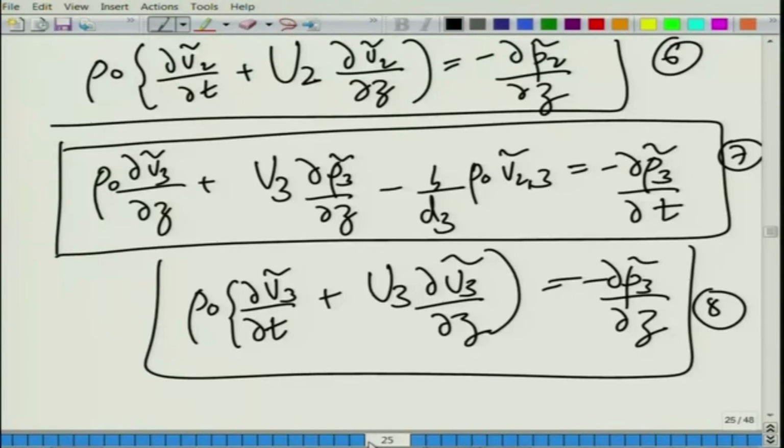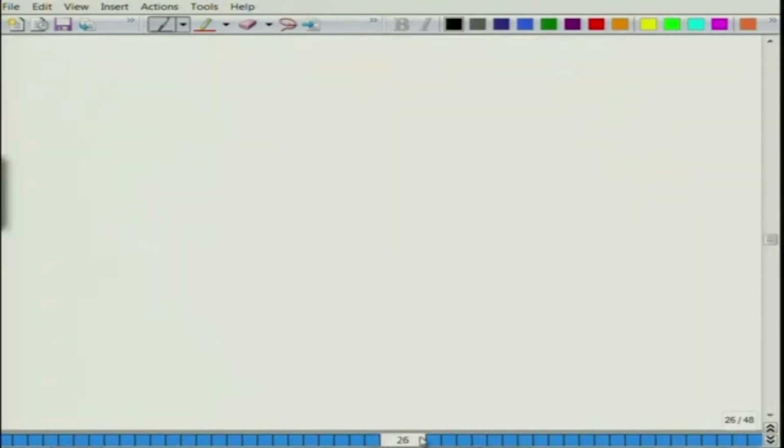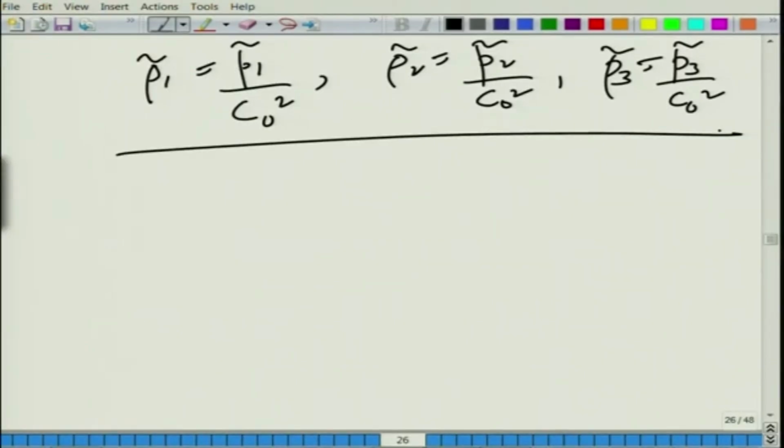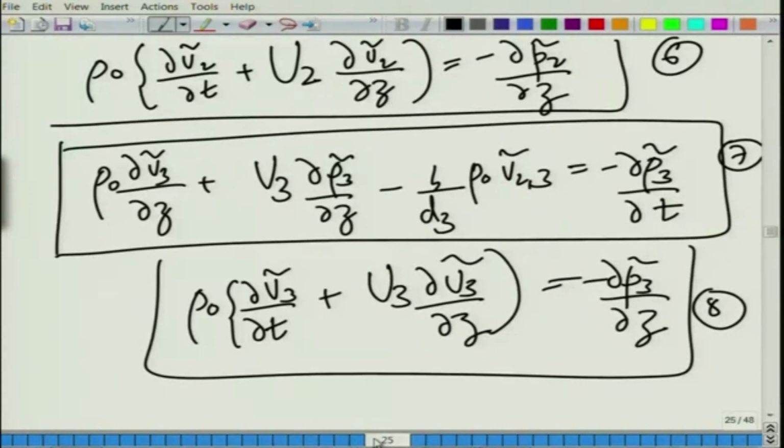So, then what we do is use the isentropicity relation. It should be fairly simple or straightforward for you to make use of such expressions, and have this. So, you have an additional 3 equations, 9 equations, 9 variables. Substitute all these into the respective places wherever they occur. As a result, your variables come down to 6, and you have 6 equations, namely p1 tilde, u1 tilde, p2 tilde, u2 tilde, p3 tilde and u3 tilde. It becomes algebraically very messy.